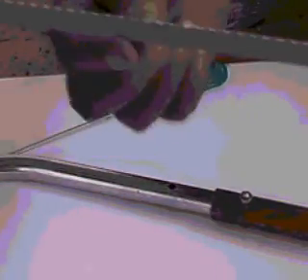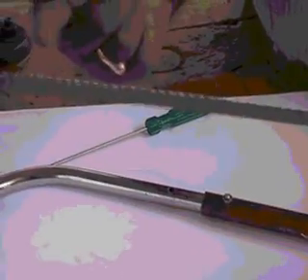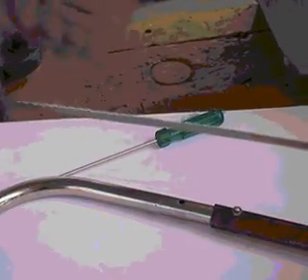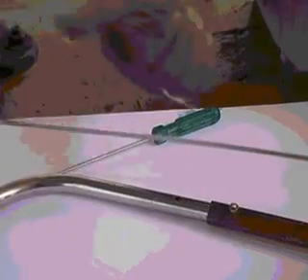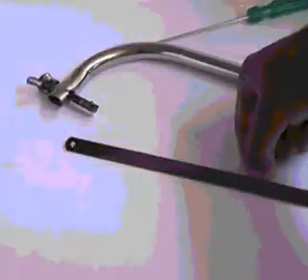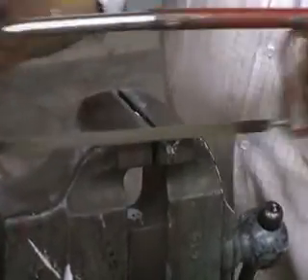While changing, remember that the angle of the teeth should be inclined towards the front, because the cutting saws cut only when they are moving forward. They cut the metal only while moving forward, and while moving backward, they come free. Look at the blade and you will be able to see the angle on the blade. This is how a job is cut using a hacksaw.